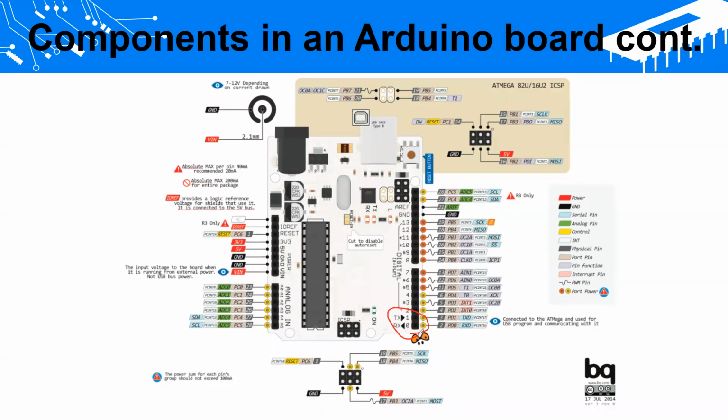So the normal behavior is, if you plug some sensor into RX and TX and you use the Arduino IDE, it can't actually burn, meaning program, the Arduino controller, right? In that case, you have to pull out the connected pins after you program it. Then you can plug in your pins, right? So that's the normal behavior.